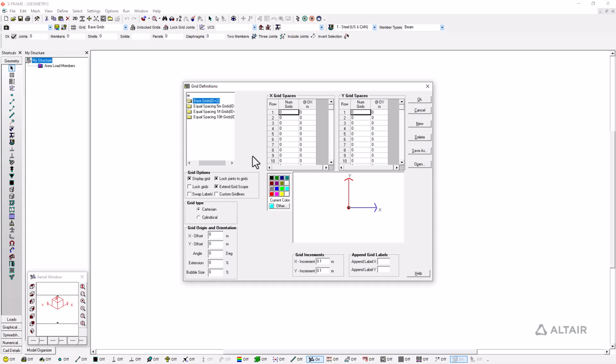So we're actually going to start creating some grids just as a demonstration here. And I'm going to work within this base grids folder set. If I just right click here, I can say new grid set, and I'm going to create a child grid underneath this. I'll start off with a rectangular grid, so I'm just going to give it a name, call it rectangular. And then I'm going to open the grid by just left clicking here, and you can see that it's currently empty.